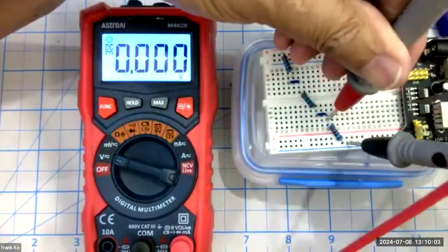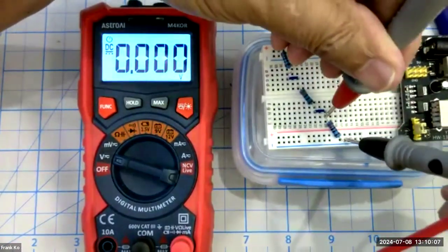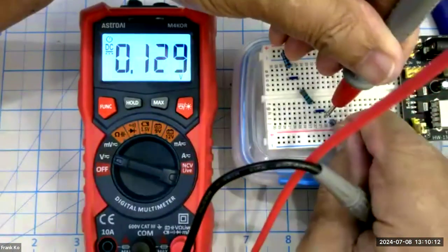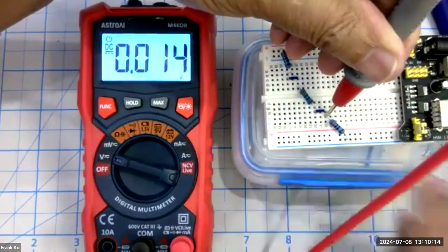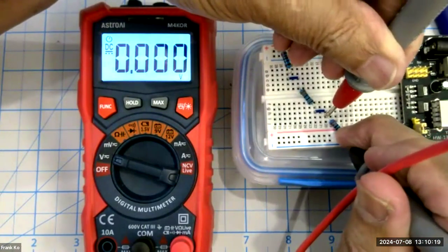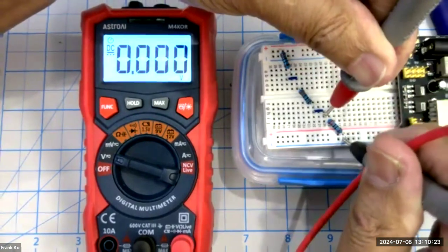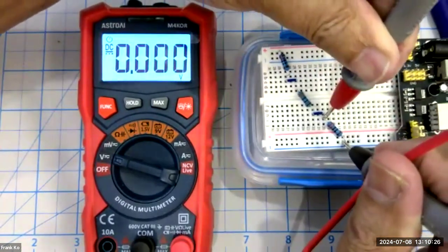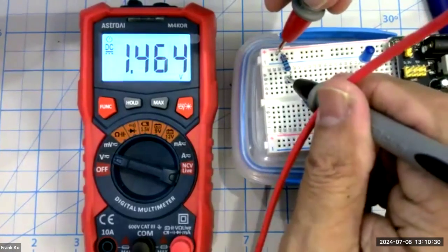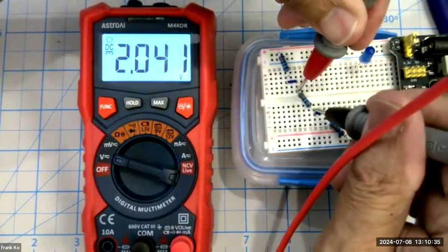And this is a good troubleshooting sequence. I'm not measuring the voltage I should be measuring. So that tells me a couple of things. Either one of the leads is now, because I smashed this onto the board a moment ago, this lead may not be all the way down. If I push this all the way down, and push this all the way down, do I have the voltage I want? Ooh, this is a good troubleshooting sequence. Why don't I get my 1.43? So double check up here. I get my 1.43. This was 2 something.